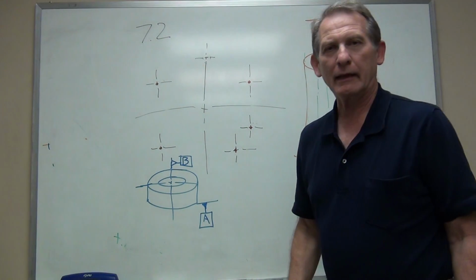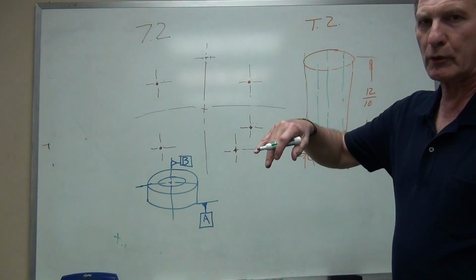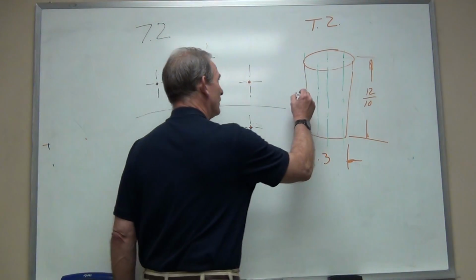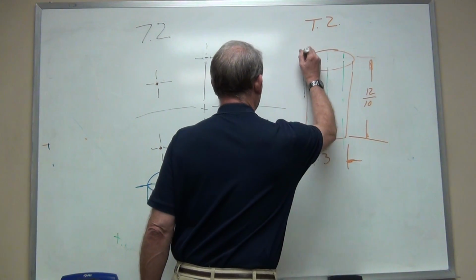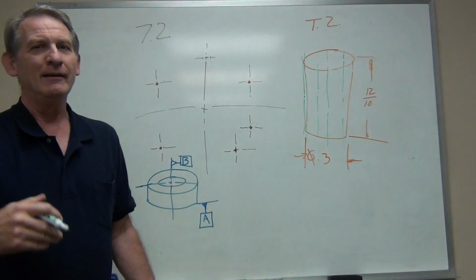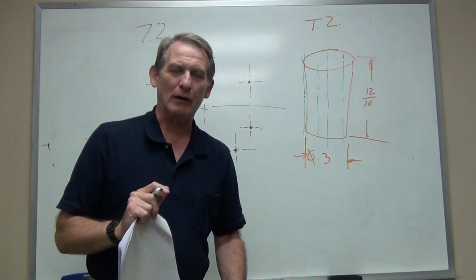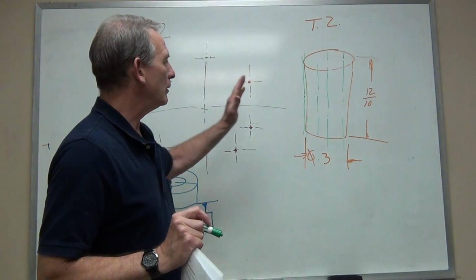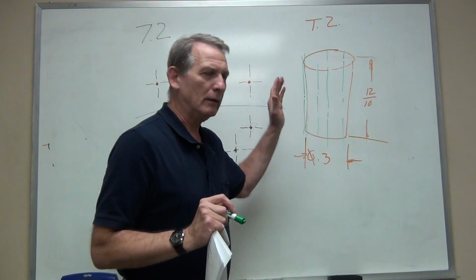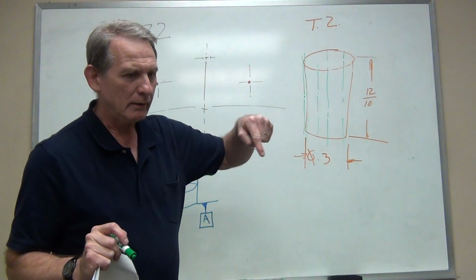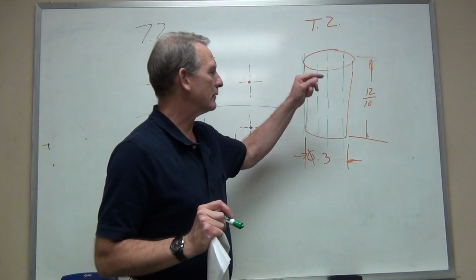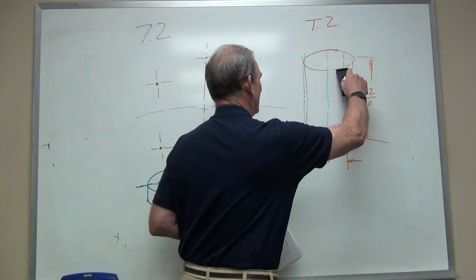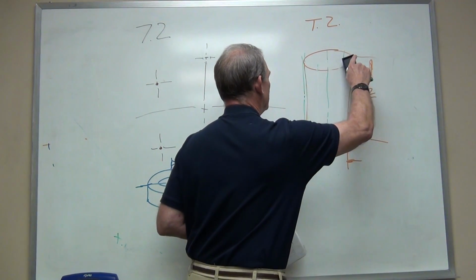And that's okay. We can take it right out to the edge or the periphery of that tolerance zone, and that'll be an acceptable part. Now, if the next part is a 1/1000th of an inch outside that tolerance zone, theoretically that is a rejected part. You are outside the tolerance zone. So you've got 0.3 millimeters running room, and if you put your holes in nice and square, they can move around a little bit on that surface within that tolerance zone. That's the translational part of it, and that is really what position is intended to control.